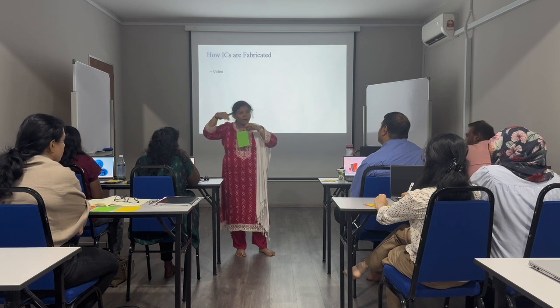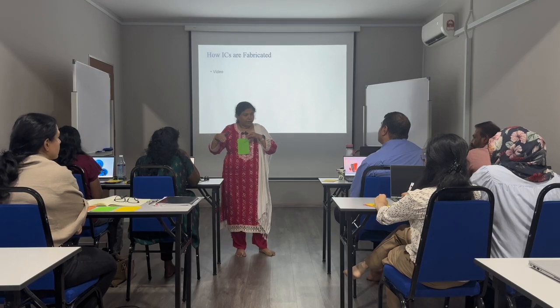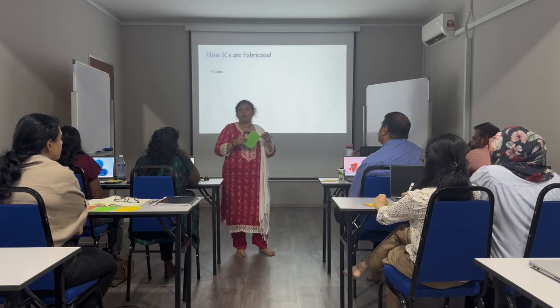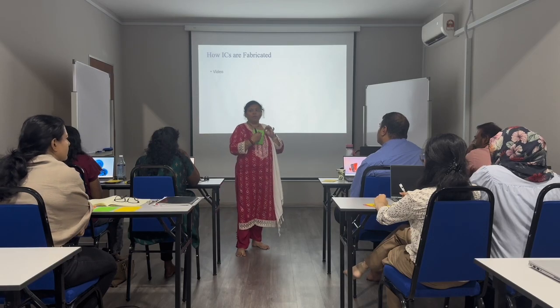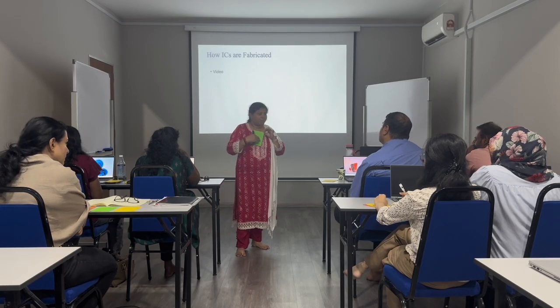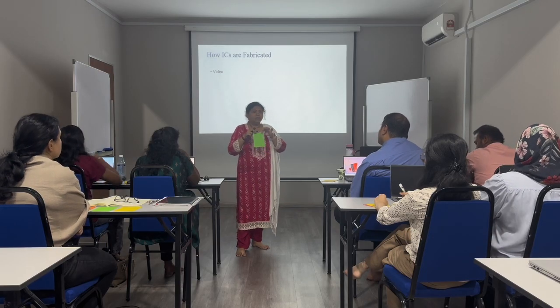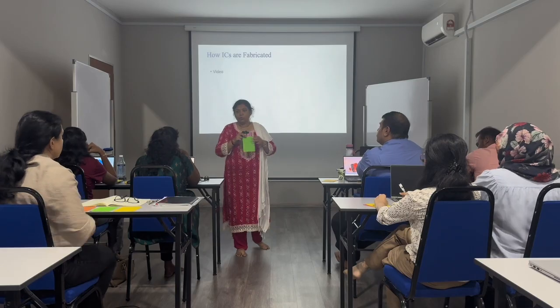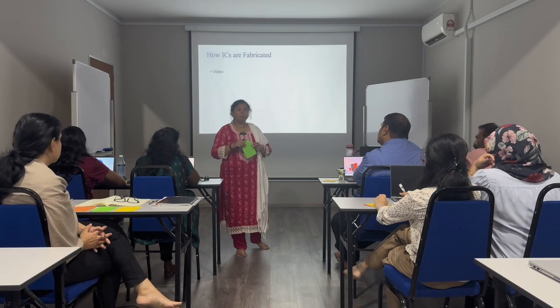This photo mask will be applied over the entire surface of the ICs, and then they will divide the IC into dice. They will go for testing, where the functional test, reliability test, and yield test are all carried out. Once this is done, they will do packaging. In a hard-bound casing, they will pack the IC and send it to the market.